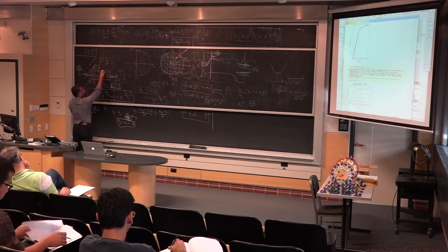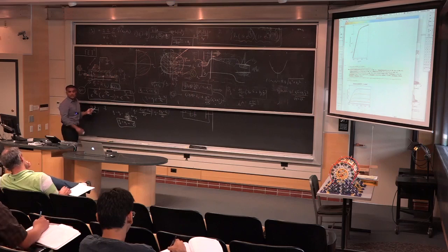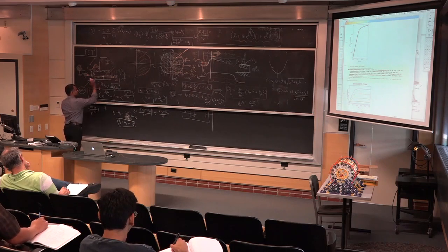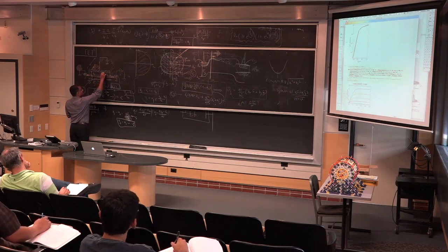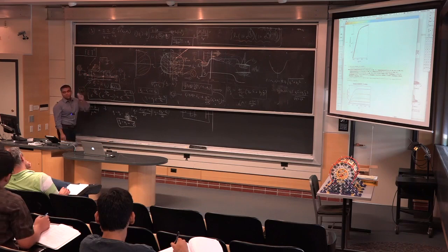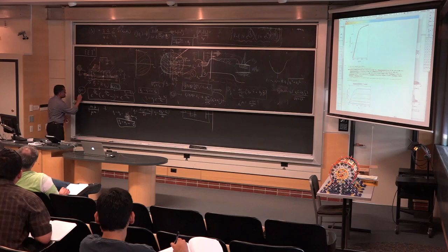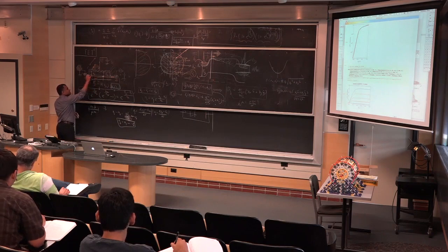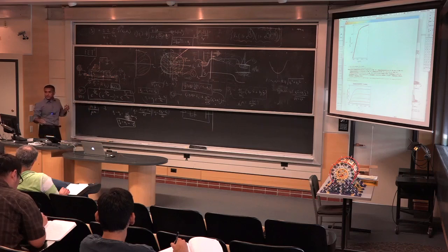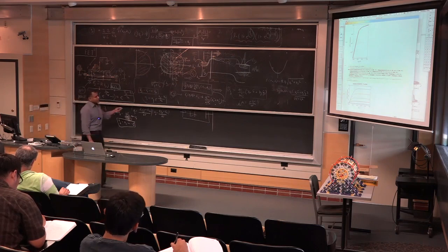Well, what is n of x? Classically, you have a parallel plate capacitor here. Forget about all quantum capacitance. Just forget about all that stuff. Classically, you have a parallel plate capacitor. This end of the capacitor is at a gate voltage minus VT. We can scale that out, VGS minus VT. This end is at an undetermined voltage. Inside the channel, it's undetermined. What is the voltage? It is V of x. We don't know. But I do know that if I reach here, I am at 0. And if I reach there, I'm at VDS. I know that. So I know the 2 boundary conditions. And that's enough. You can actually solve the entire problem with this, and that's what Shockley did.